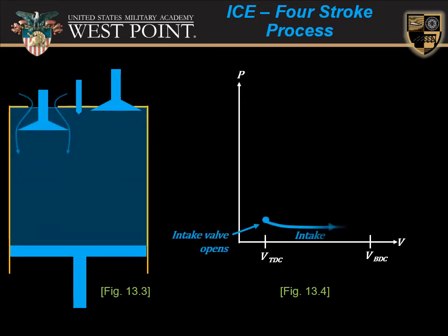On my intake stroke, my intake valve opens and I have air or an air and fuel mixture enter my cylinder. And we see that plotted on figure 13.4, where I move from top dead center to bottom dead center, at which point the intake valve will close.